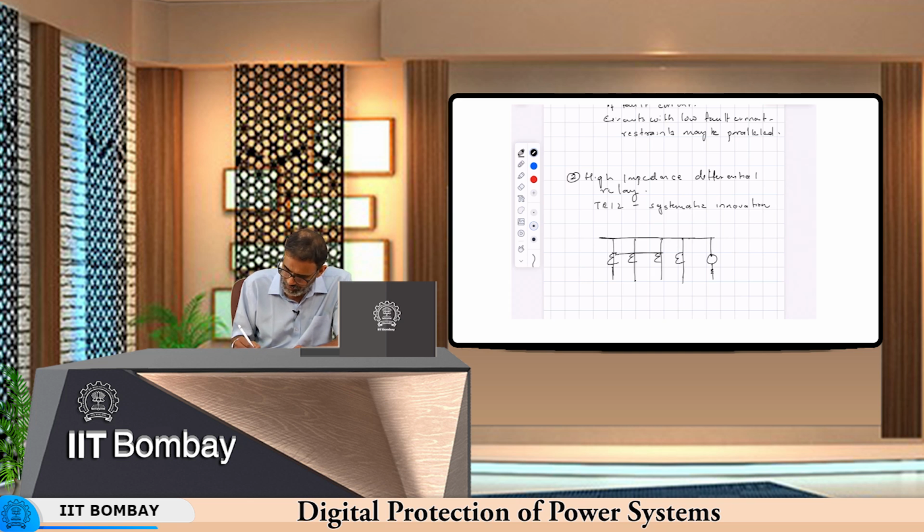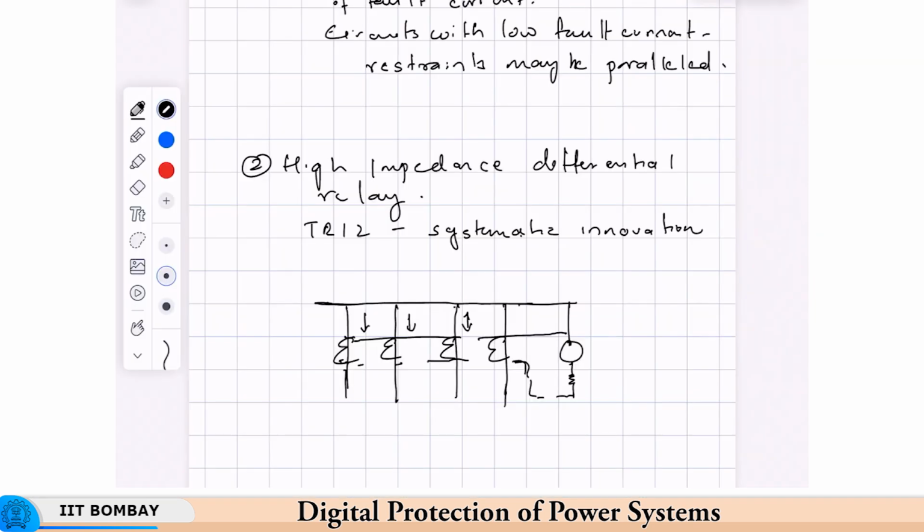Okay, so, now all the CT currents are summed into the relay, this is just drawn schematically. Okay. And suppose there is a fault here and then this CT saturates. Okay, that means its impedance goes down drastically.